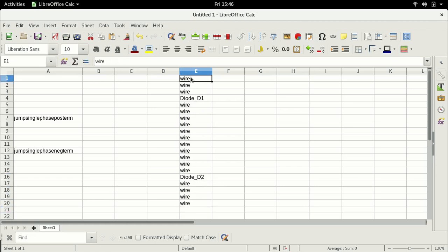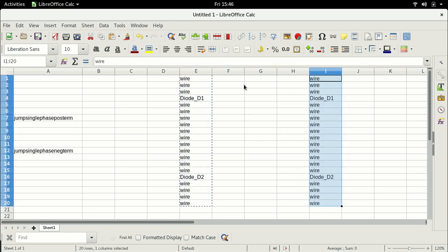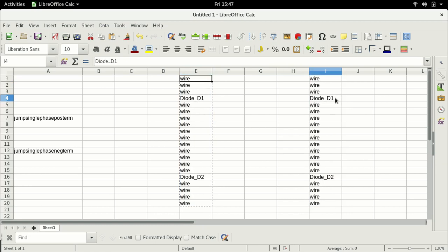So this is one leg of a diode bridge. I'm going to copy this and put it here. This is my second leg. So I have to change the name to diode D3, diode D4. As before, you can also name this descriptively, it's up to you, and I would suggest you should name it descriptively.